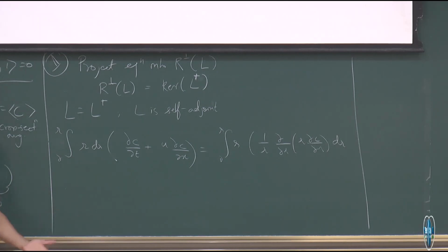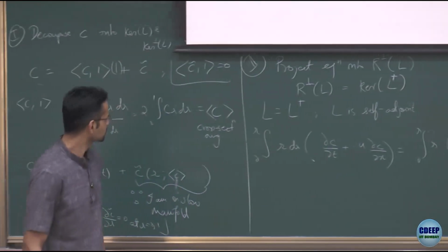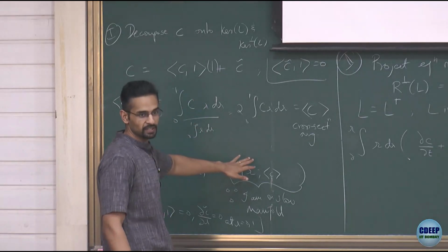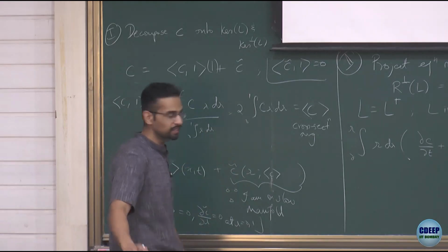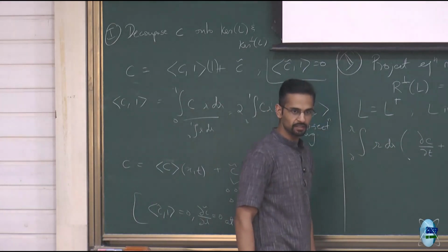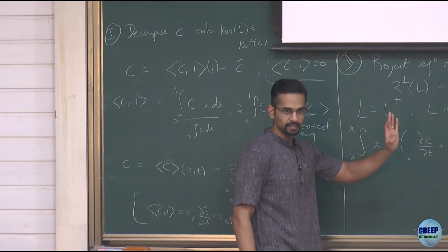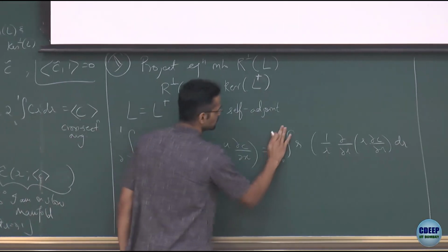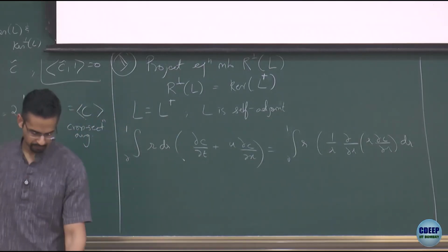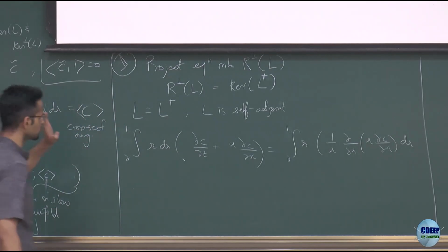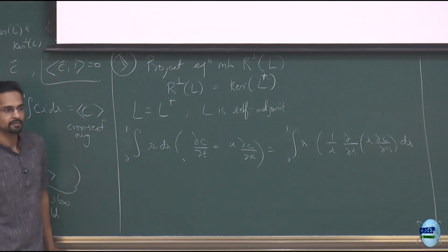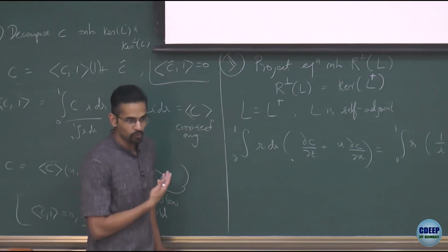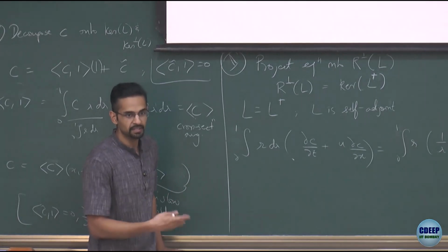But it's nothing but taking the cross-section average of the equation. Once again, because you have this nice interpretation, the split in the domain space was to project the concentration field into its cross-section average plus deviations, and then you take the original equation and average that also. You just take the cross-section average of the equation, from 0 to 1. So because in this problem the kernel vector is very simple, it's just 1, what we do with this advanced technique ends up being the same as some naive averaging.